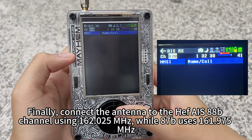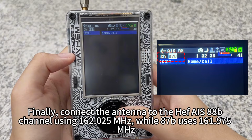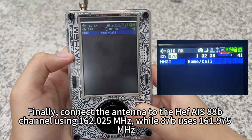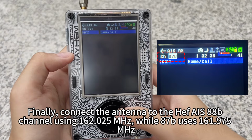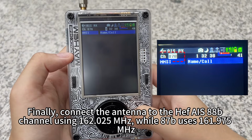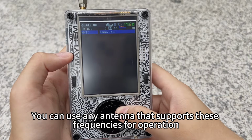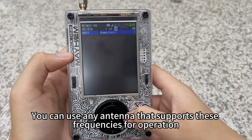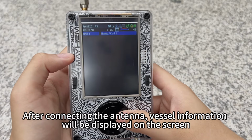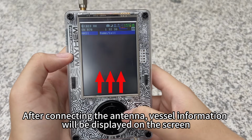Finally, connect the antenna. Channel 88B uses 162.025 MHz, while 87B uses 161.975 MHz. You can use any antenna that supports these frequencies for operation. After connecting the antenna, vessel information will be displayed on the screen.